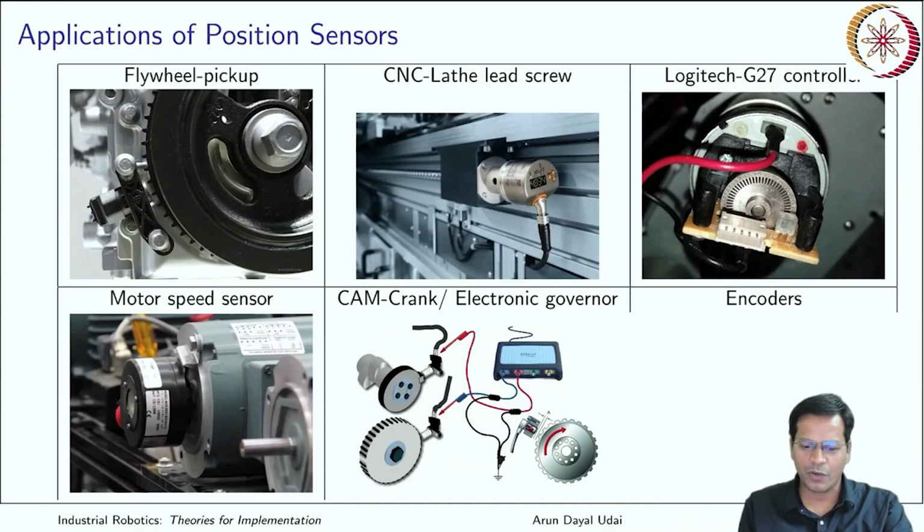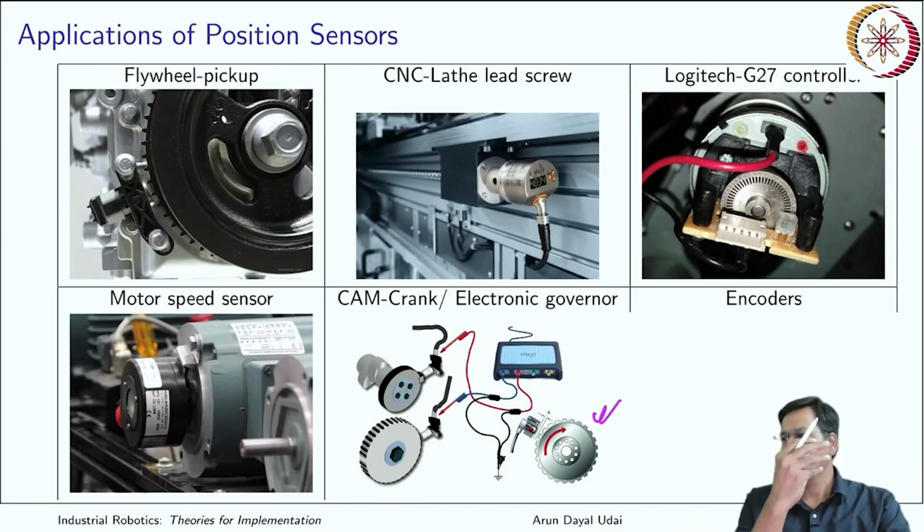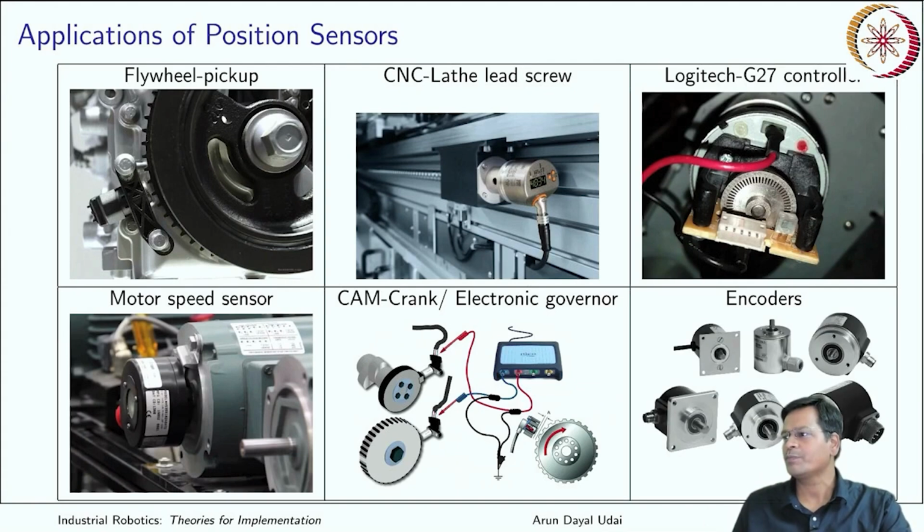So that is measured continuously, and its velocity is fed back and maintained using a type of controller, the electronic governor system. So the electronic governor continuously takes feedback of speed and maintains that speed using the fuel rack system. Okay, so that is what is there in the electronic governor.